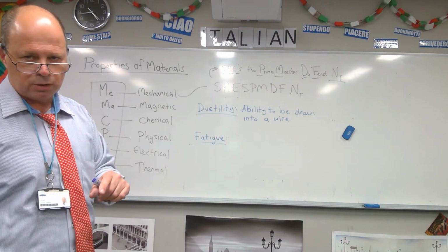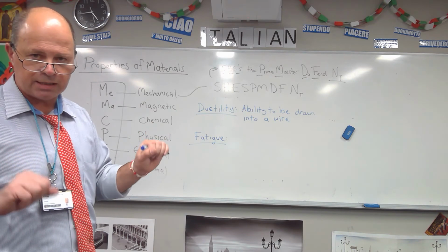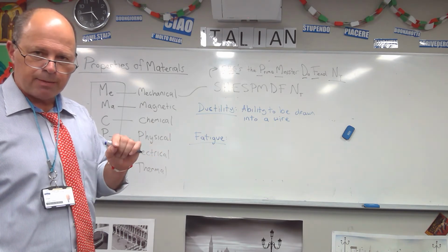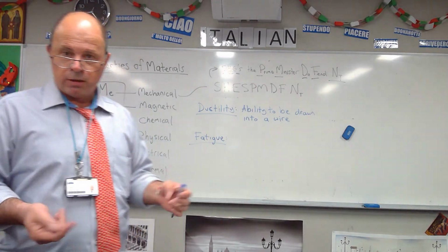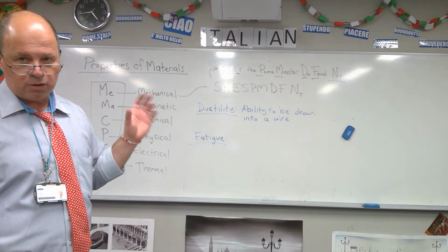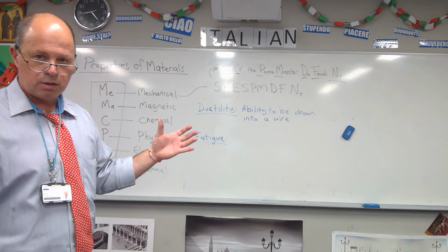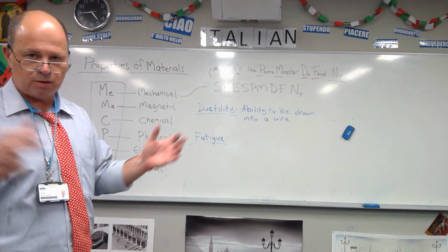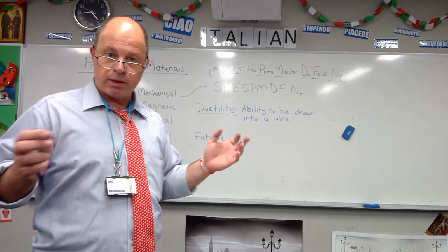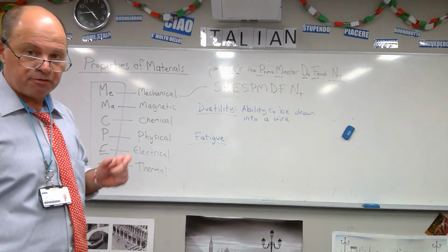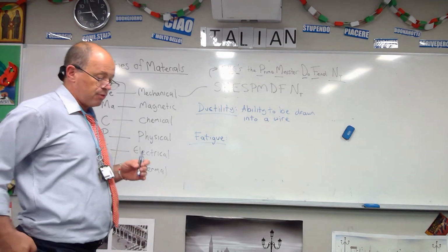That is true, but certain materials, if you cycle them even below their elastic limit enough times, they'll form cracks, and the cracks will get bigger and the material will fail. And this is something that we found out in the early days of jet aircraft, especially with pressurized cabins. You pressurize a cabin within its elastic limits, you unpressurize, pressurize, unpressurize. Eventually, because of that cycling below the elastic limit, the material will fail, and it's called fatigue failure. Okay, so it's a special type of fatigue failure.